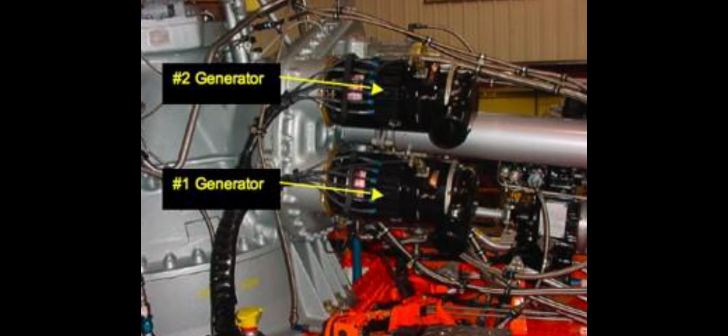Current transformers. Three current transformers for each generator sense the flow of each phase of the generator output feeder line. Each current transformer consists of a number of turns of wire which function as secondary winding, and the transformer is mounted around a generator feeder line that serves as a primary winding. When the generator is supplying AC power, the current transformers produce outputs corresponding to the current flow in each respective feeder line. The transformers for each generator operate in conjunction with the feeder fault transformer, which monitors the current flow of each of the three-phase generator ground return lines.